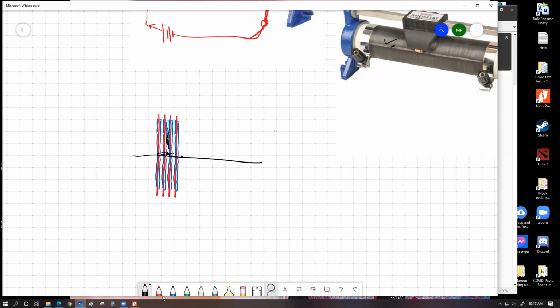Yes, sir. This is a good example, but I think it works because you can visualize it easily. So that's pretty much what happens for this part of the coil: by the rubbing of the copper teeth, it actually removes a small bit of insulation on the surface and can make actual electrical contact with the inside wires. However, the wires remain insulated from side to side because the copper teeth only remove the insulation on the top portion. It doesn't remove any insulation for the in-between wires. The in-between wires' insulation is still intact.